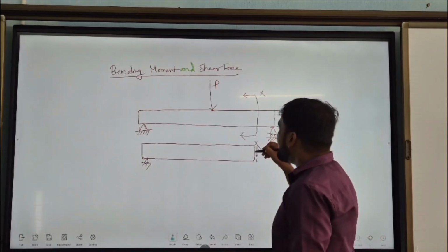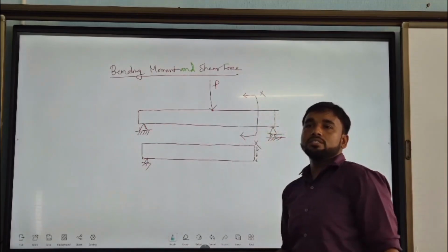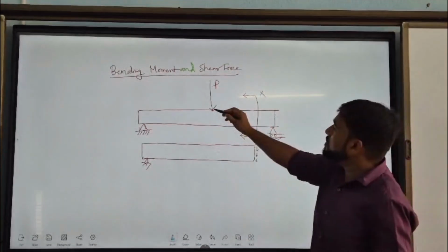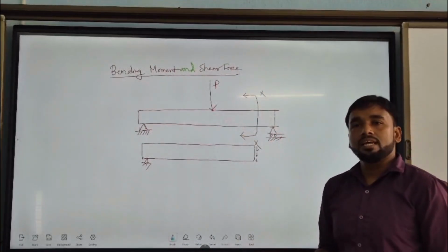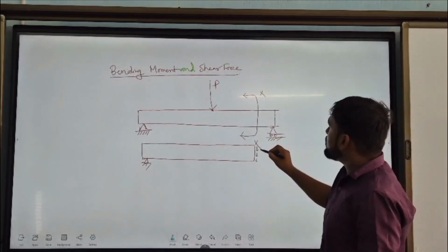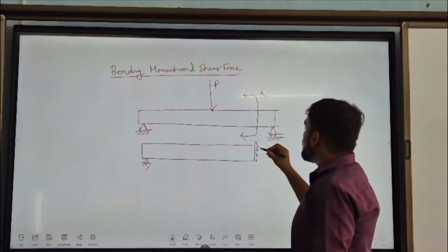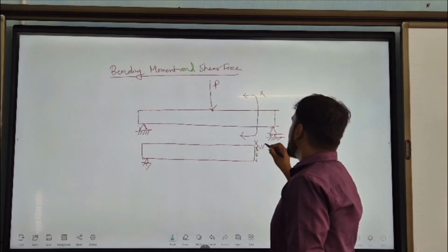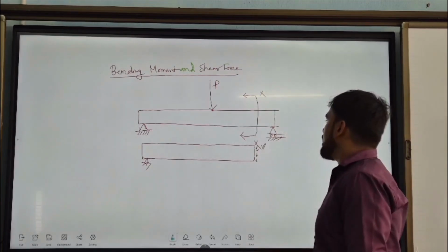This is nothing but internal forces. Because what is stress? Stress is nothing but the internal resistance. Because the beam is loaded, some resistance of the beam will be there. That internal resistance will be the shear force, the vertical force. This is your shear force. Shear force will be there.